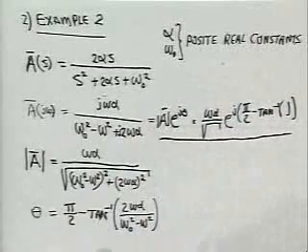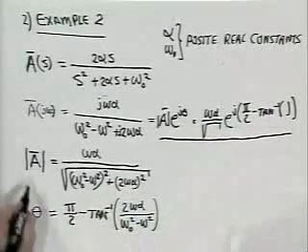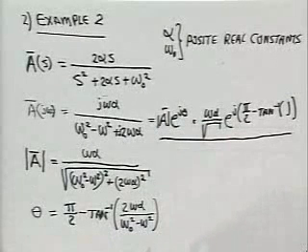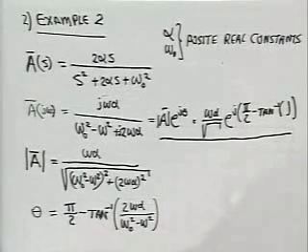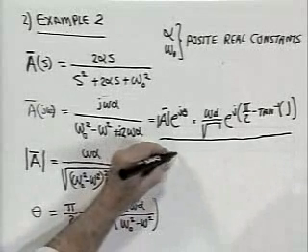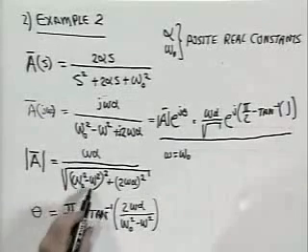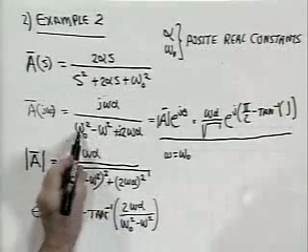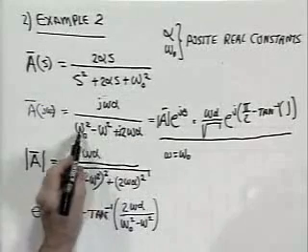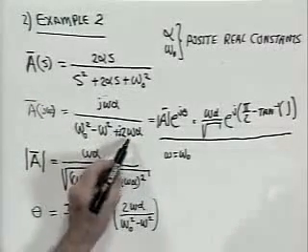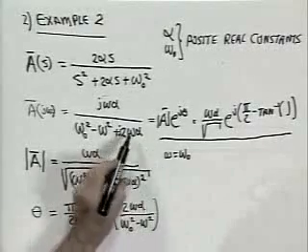And we're now in a position where we can look at the behavior of the angle and the magnitude for various frequencies. One frequency of interest is when omega equals omega naught. At that frequency, the real part of the denominator disappears. This is 0. I'm just left with j 2 omega alpha downstairs.